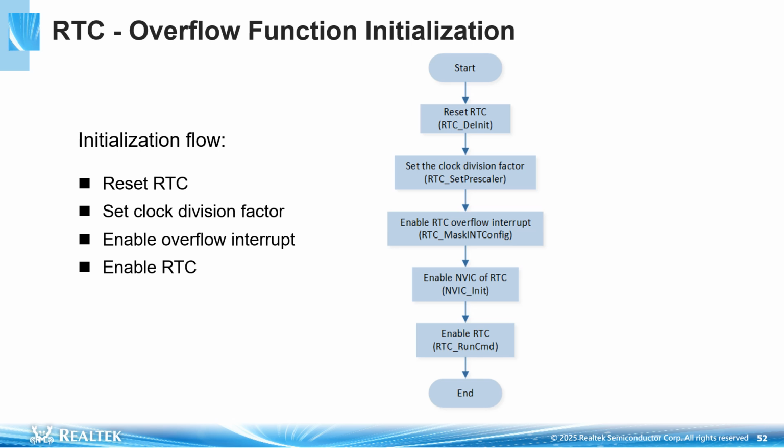The initialization process of RTC overflow function is shown in the figure. Firstly, reset the RTC, set the clock division factor of the RTC, then enable the RTC overflow interrupt, and finally enable the RTC.